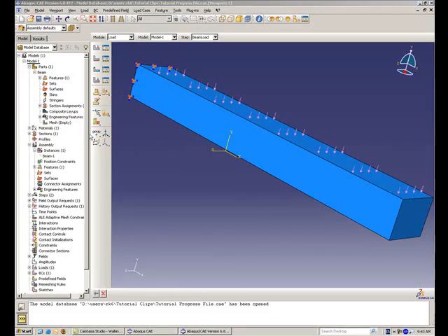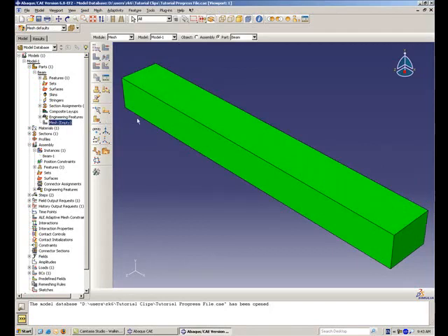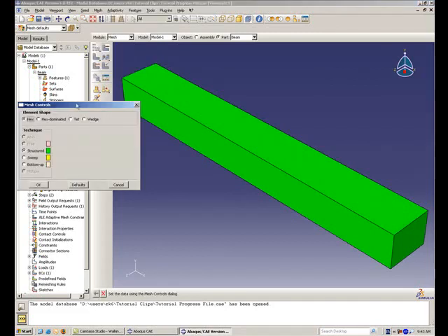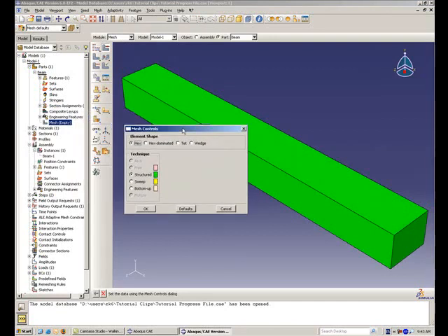The final step before starting the analysis is meshing the part. Start the process by expanding the parts and beams branches of the model tree, then double-clicking on the mesh container. Abaqus automatically switches to the Mesh module. From the main menu bar at the top of the screen, select Mesh and then Controls. Accept Hex and Structured as the default element shape and technique selections.